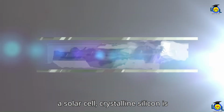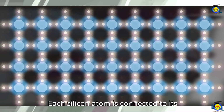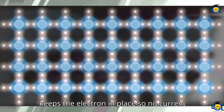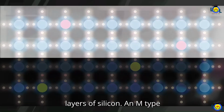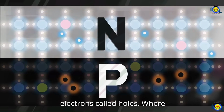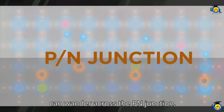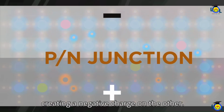In a solar cell, crystalline silicon is sandwiched between conductive layers. Each silicon atom is connected to its neighbors by 4 strong bonds, which keeps the electron in place so no current can flow. Here's the key. A silicon solar cell uses 2 different layers of silicon. N-type silicon has extra electrons, and P-type silicon has extra spaces for electrons called holes. Where the 2 types of silicon meet, electrons can wander across the p-n junction, leaving a positive charge on one side and creating negative charge on the other.